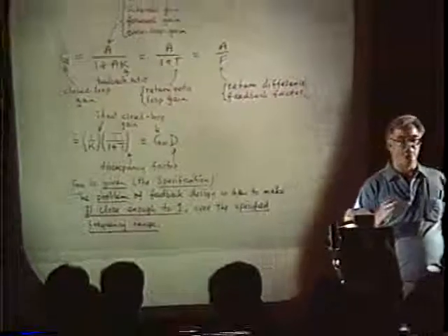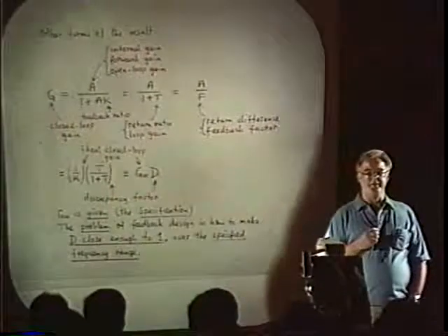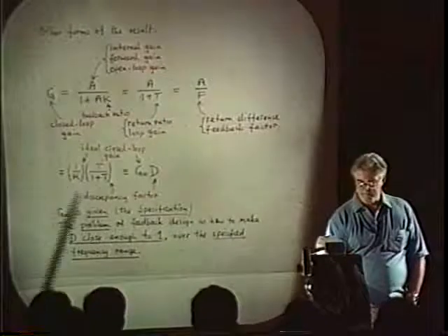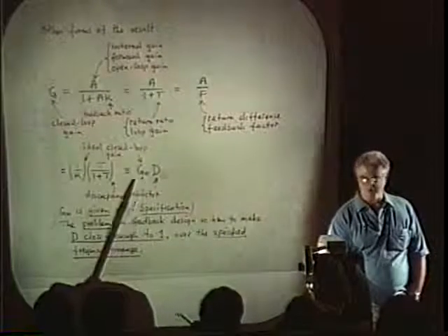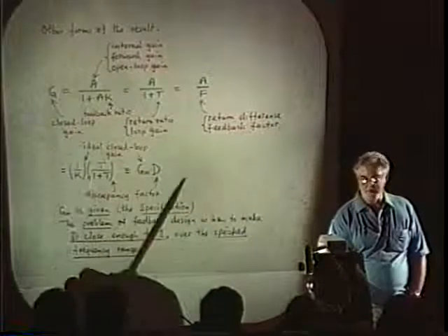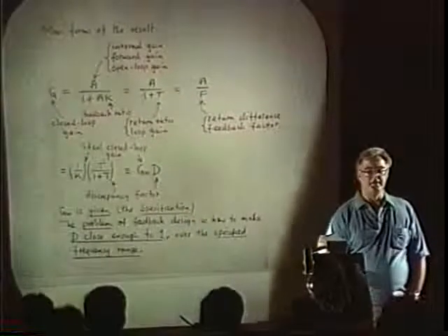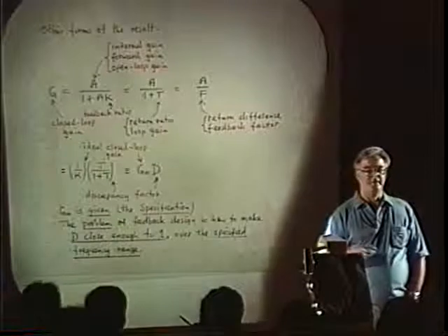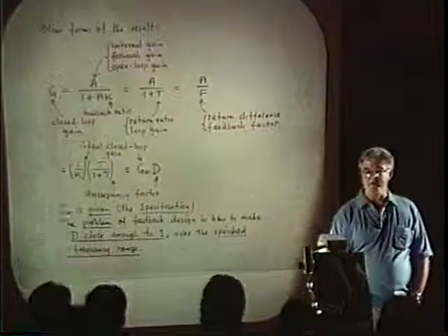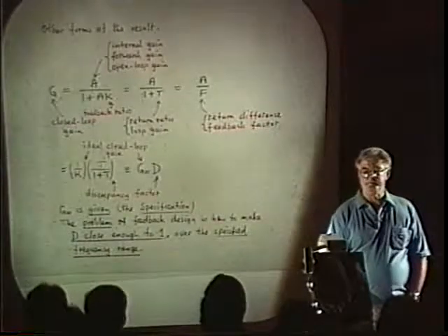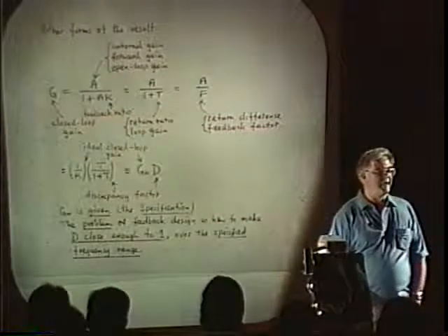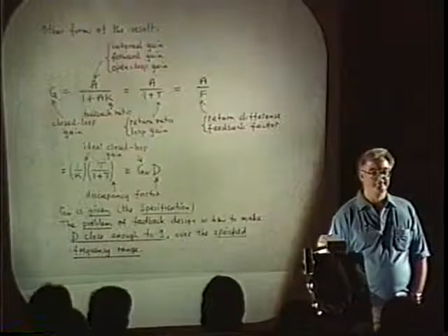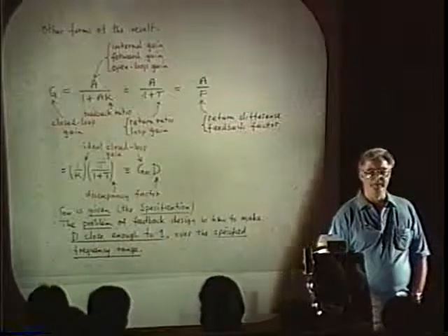That defines what your design process is for a feedback system. Define the K box directly from the specification, and all you have to deal with is T. T is the single central parameter that determines the actual closed loop gain. Notice that the A has vanished. You don't need it.